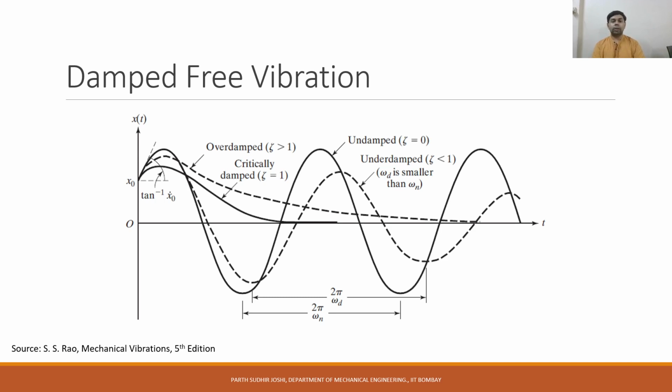You might have seen this in offices, where if we open a door and release it, it has a mechanism to close the door automatically. There is a piston cylinder on top of the door above our head. That is the damper that is used. When we open the door and release it, it will slowly close and then finally stop.